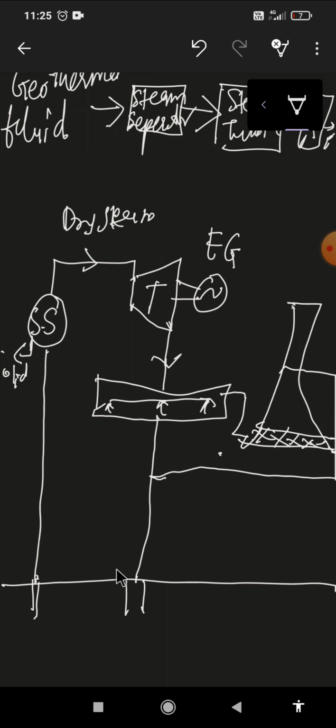And the reasons for reinjection of condensate into the earth are: first, why are we reinjecting it back into the earth? To ensure the supply of fresh water from the production well for several years, the earth acts as a steam generator. Second, to prevent environmental pollution, since the condensate contains certain pollutants. For example, steam at the Geysers contains hydrogen sulfide. If condensate is left out on the ground layer, it causes environmental hazards.